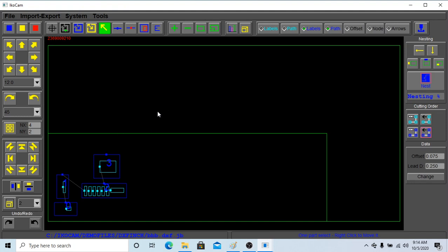Like to move a part, you select it first and then move it, but before you have to select steps. It will jump for 1.5 inches now, left, right. Also, you can use Control and arrow left, or Control and page up for rotating. Now I will delete this part. And what else?